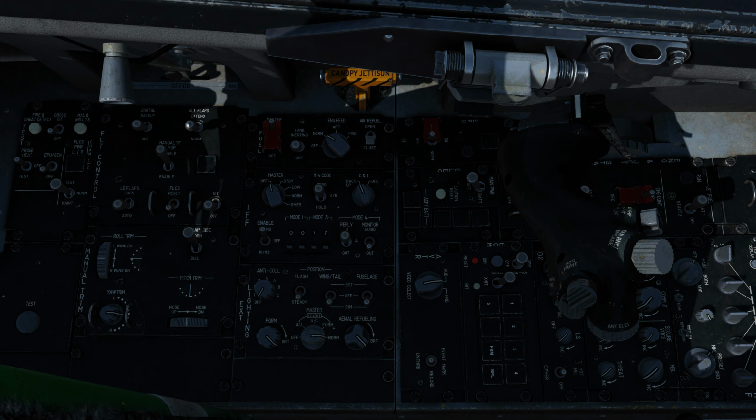In SEC, the MEC provides fuel flow scheduling, in addition to the functions it provides in primary operation. During SEC operation, the SEC caution light is illuminated, afterburner operation is inhibited, and the nozzle is closed, raising idle thrust.